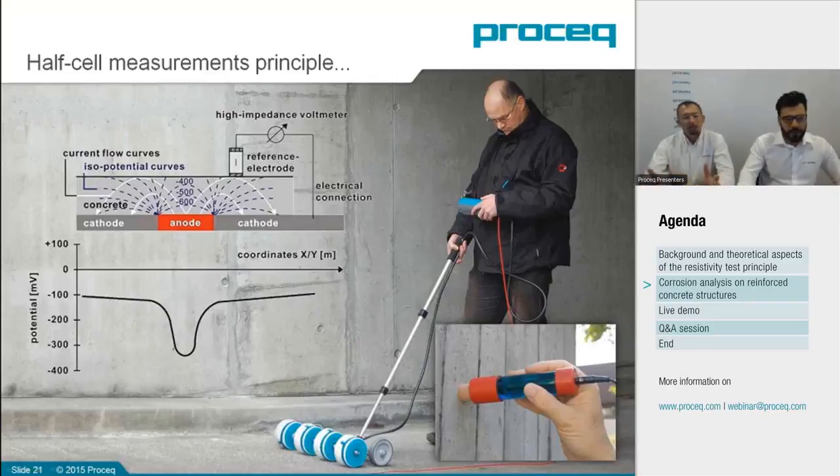Of course, it's all a matter of the grid that you want to have, but let's say on a suggested grid of 25 by 25 cm, with that four-wheel thing, you can count, once everything is set, on a productivity of around 1,800 square meters per hour, which is absolutely not reachable with traditional.